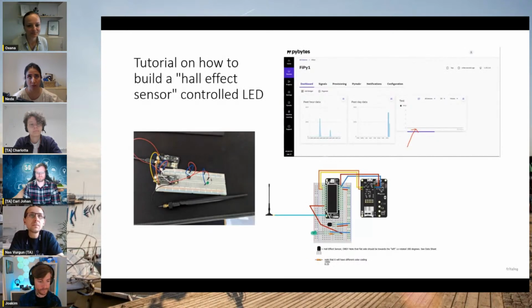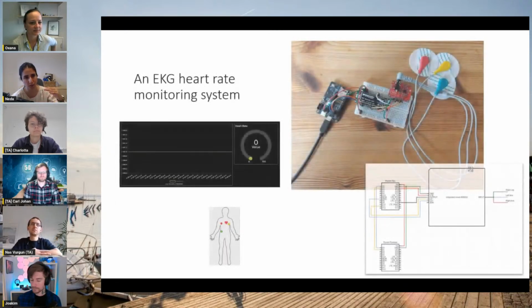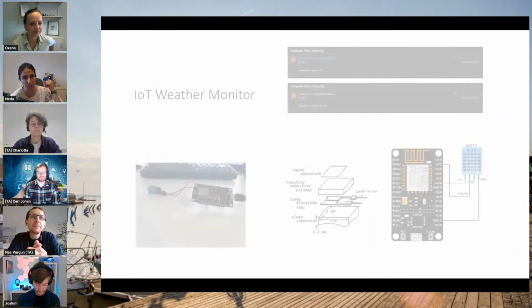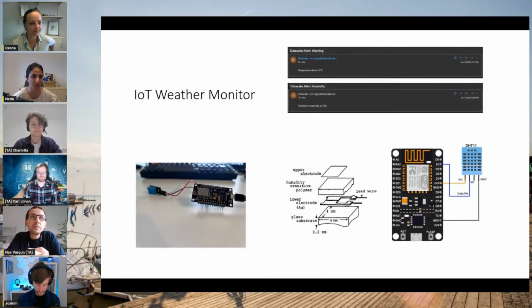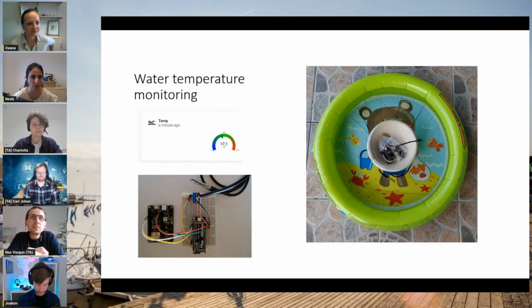And we also have a pilot case called Kalmar Damm, where we have installed some sensors for conductivity and distance sensors that measure the distance to the water level and also the conductivity of the water, installed in that dam close to the airport. And then we get the data and send it via LoRa to the dashboard. So it was one of the pilot cases as well, using LoRaWAN.